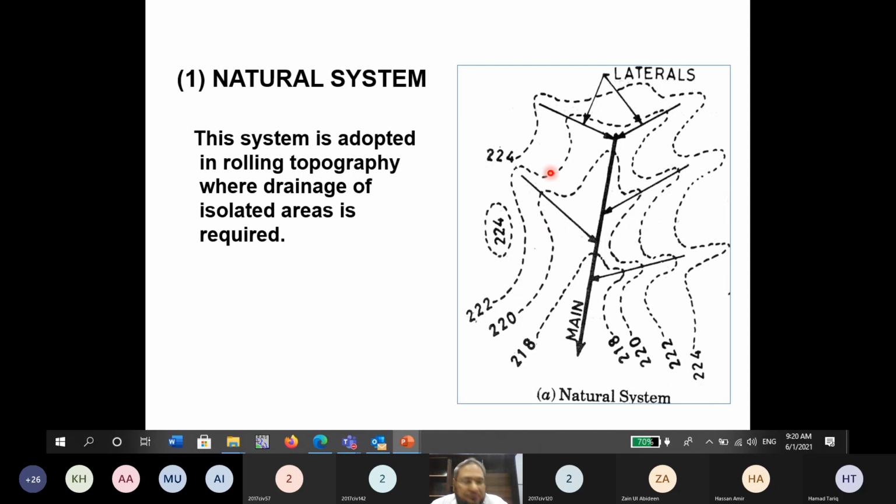In the contour lines, if we have sharp curves like these, what do they indicate? It is a hilly area, so what will this indicate? Either this will indicate ridges and valleys. It will show either a valley or a ridge. Now how can I know whether it is showing a ridge or a valley? You know how much the elevation is here?